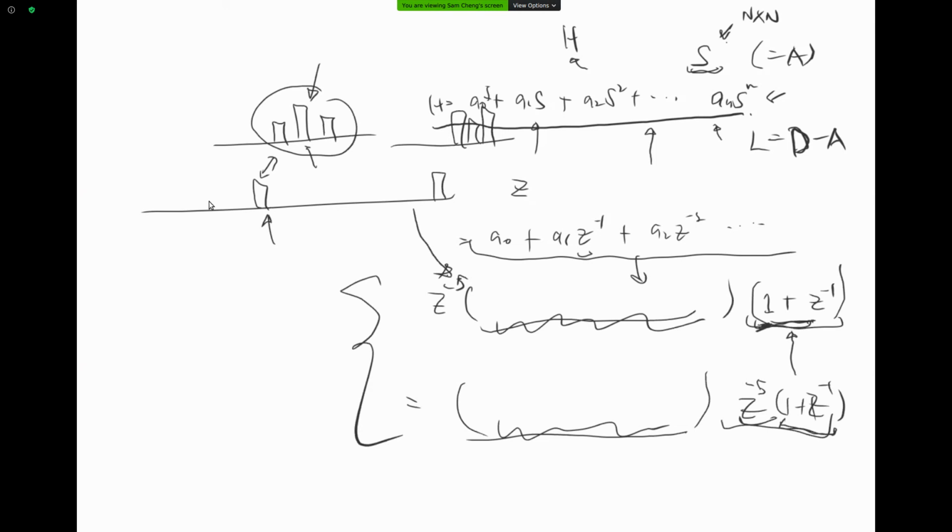And an immediate consequence, as captured here, is that if I have an incoming signal, and I shift that signal for some time and then apply the filter, it will be just the same as applying the filter directly to that signal and then shifting it. Also, you can see that the shift operation and the filter itself actually commute. More generally, if I shift one step, it's just an S operator. So I have S multiplied with my filter equal to the filter multiplied by S.